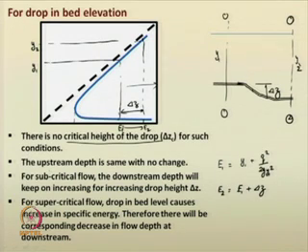You will also see that the upstream depth will remain the same, with no particular change in the flow profiles. For subcritical flow, the downstream depth will just keep on increasing as you increase the drop height. For supercritical flow, the drop in bed level